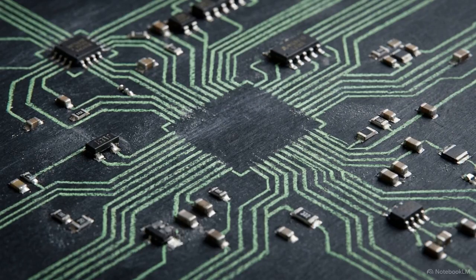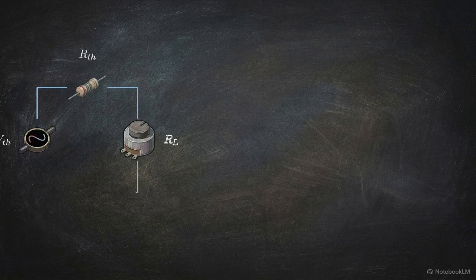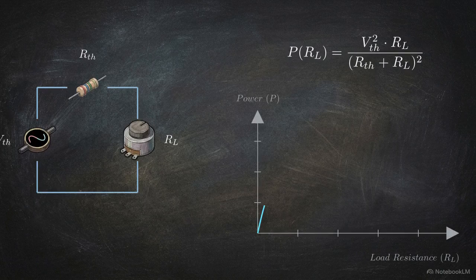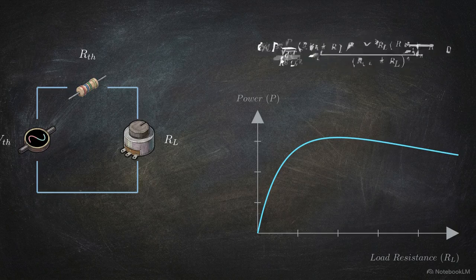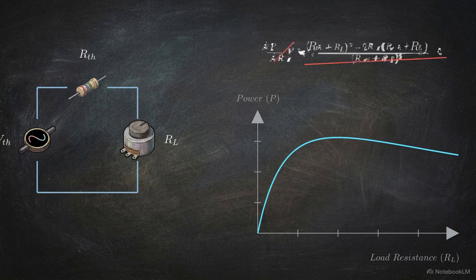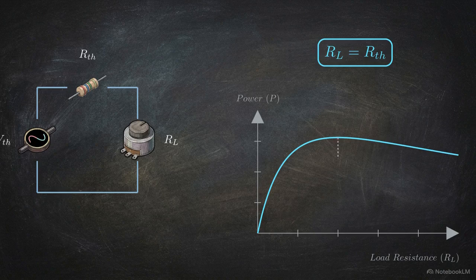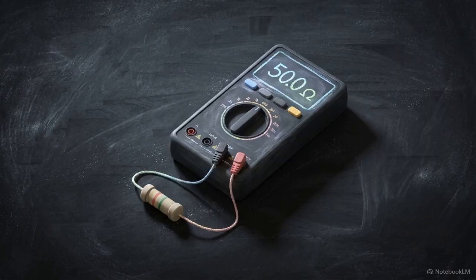We see the exact same mathematical logic govern circuit design, specifically when solving the problem of delivering maximum power from a source to a load. Our circuit's source voltage, internal resistance, and variable load resistance trace a parabolic power curve. Setting the first derivative of power to 0 simplifies the complex fraction, proving the absolute peak occurs exactly where load resistance perfectly matches the internal source resistance. Analytical calculus proves that maximum power transfer is mathematically impossible unless the two resistances are identical.